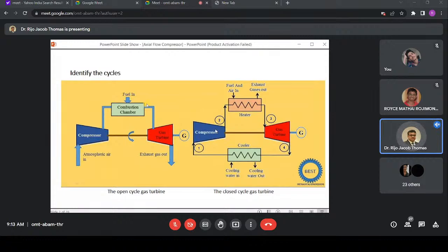If the fluid density is high, the work of the compressor can be less. The size of the heat exchanger can be less. The turbine with a smaller size can produce the same work which it produces otherwise. Here also the heat exchanger can be small. But in the open cycle, we can use only air or oxygen as the fluid because you want combustion to happen.